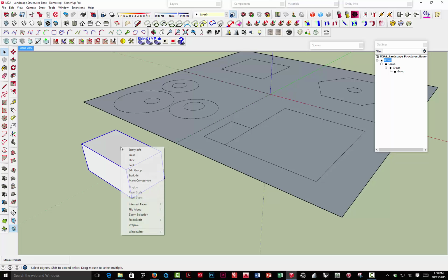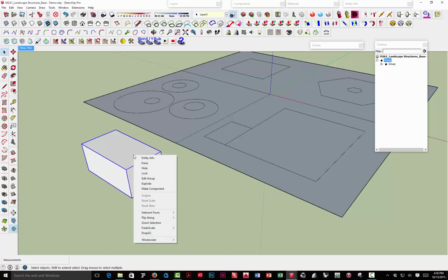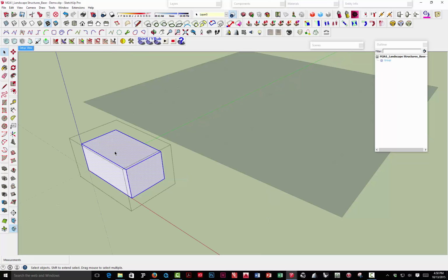So if I had this, I would right click, explode, select, right click, explode, select, right click, explode. So now I have one group. So when I open this group, if there's only one piece of geometry in here, that's all you need. So nested hierarchical groups are really important, but nesting the same geometry 3 or 4 times as a group really just makes your job a whole lot more difficult. So that's one of those conceptual things that you need to think about and understand.